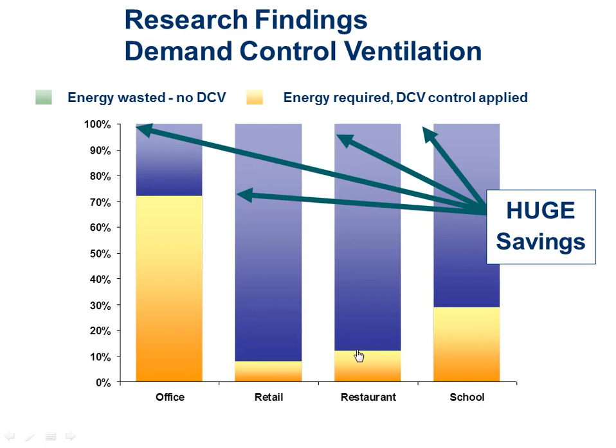Restaurants, similar story. They're designed for whatever the Saturday evening crowd or whatever their peak time is. So there's lots of ability to ramp that ventilation down. This is showing you basically an 85% reduction. However, I will caution you with restaurants. Unfortunately, most restaurants in the dining room area, they've used the ventilation system for the dining room to be the makeup air system for the kitchen exhaust hoods. Obviously, a good design, I'd have makeup air in the kitchen at the hood, but sometimes they don't do that, and they provide the ventilation air through the rooftops in the dining area of the restaurant and suck it through the doors into the kitchen. So if they're doing one of those kind of deals, I can't really cut back the outside air. Otherwise, I'm going to starve off the exhaust hood.